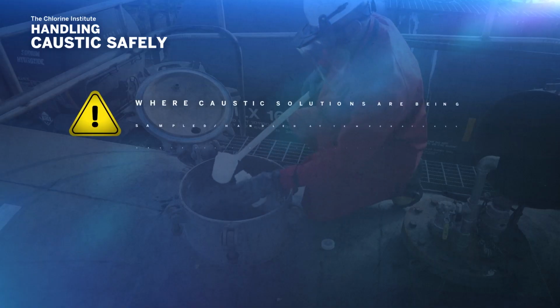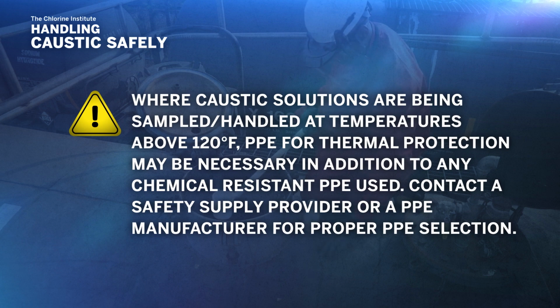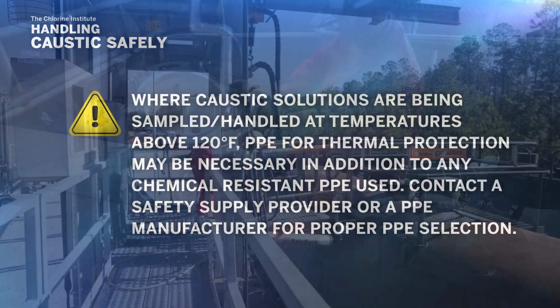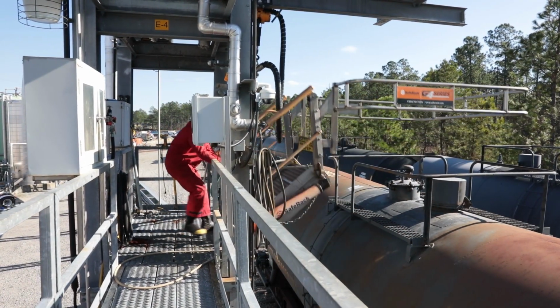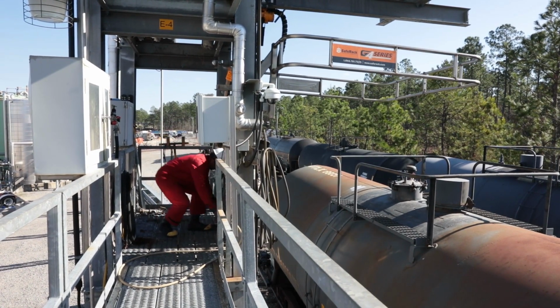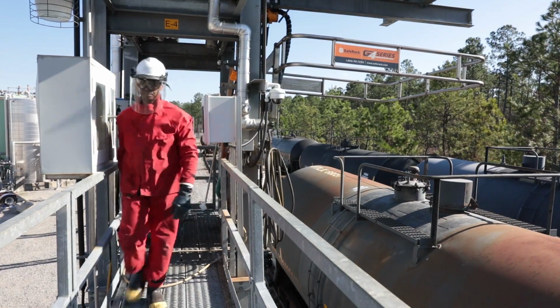Where caustic solutions are being sampled and/or handled at temperatures above 120 degrees Fahrenheit, PPE for thermal protection may be necessary in addition to any chemical-resistant PPE used. Contact a safety supply provider or a PPE manufacturer for proper PPE selection. Use of protective equipment reduces the possibility for exposure. However, there are other precautions that can be taken to reduce the likelihood of injury should an exposure occur.